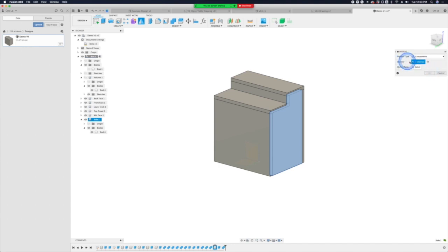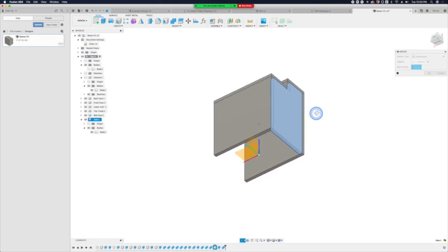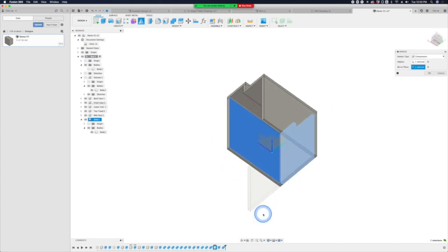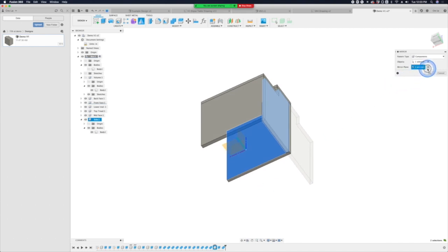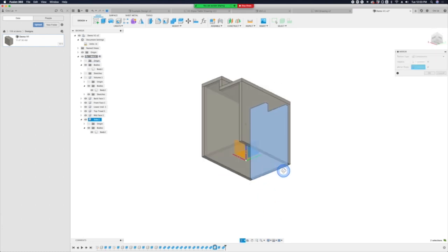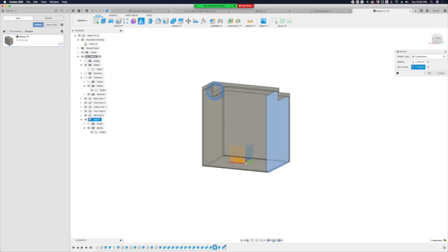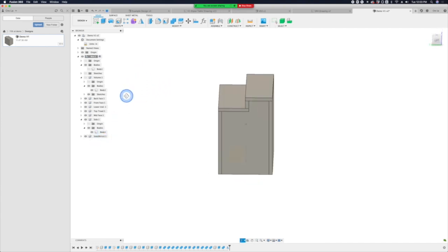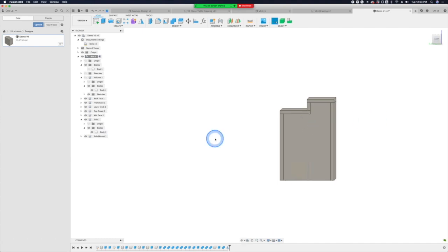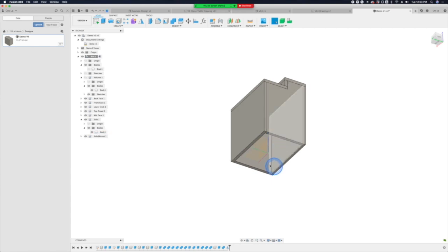Okay, so select what you want to mirror, and the plane that you want to mirror it across. If I select this face, it's going to flop over there. But if it was the wrong one, I can select this center point. Yeah, and that's what I want because I know that our model is centered over this. And now we have our side mirrored. It tells you.